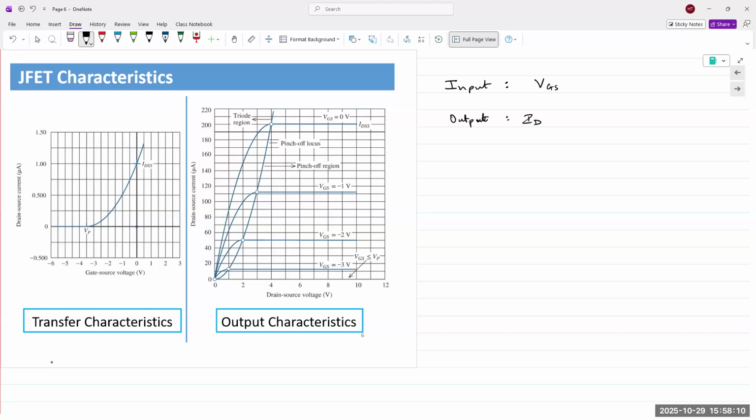And the way it works is for FETs and for BJTs and for MOSFETs, on the input side, you change the input by 1 step. And on the output side, you sweep your voltage from, let's say, 0 to 10, 0 to 15, 0 to 20 volts. And then you collect your output current.